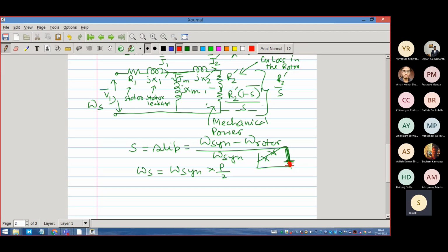So that's why sometimes they say that the induction machine is a constant speed machine, because you see that the speed is hardly varying. In this small zone, the torque will be varying, but hardly the speed. You must understand that this zone is much more extended than this straight line zone.